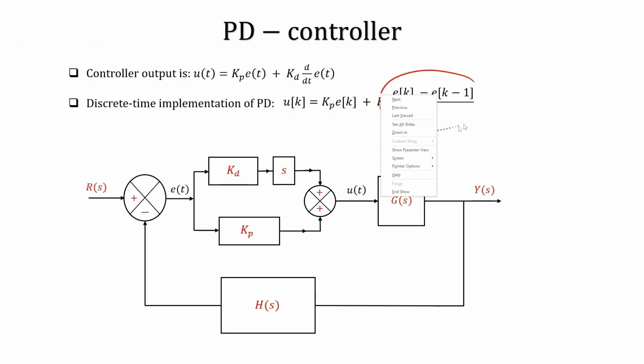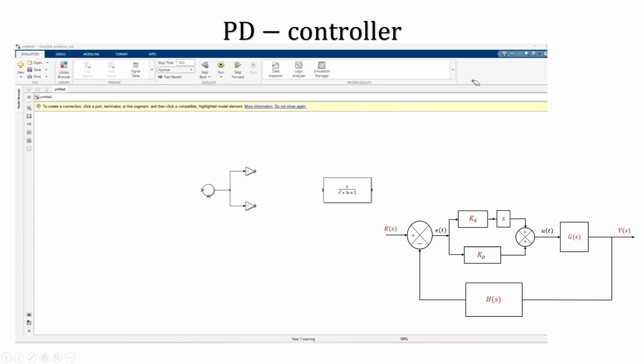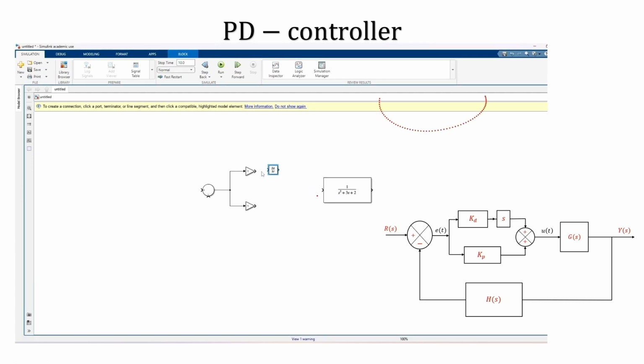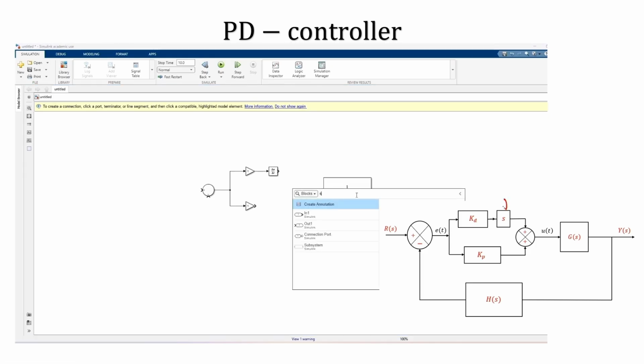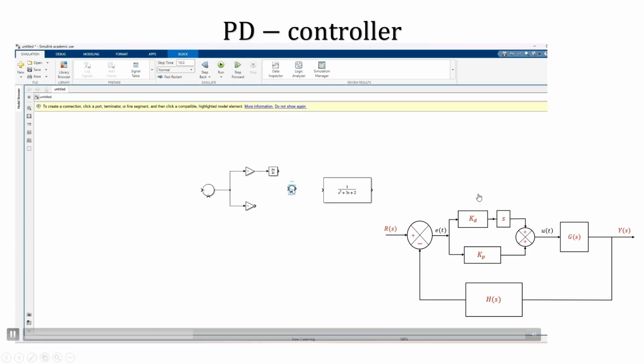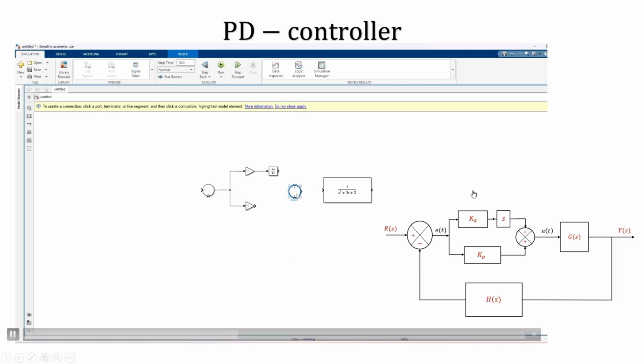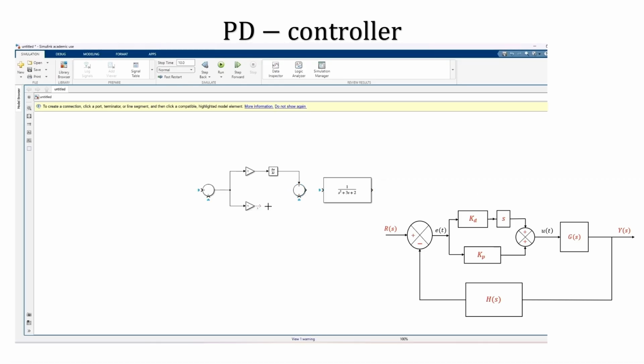Okay. Now, how do I ensure that this has been implemented? In Simulink, in place of the transfer function I can use what is known as a derivative block. It computes the approximate continuous derivative of a continuous function. Using this block you can implement the derivative part of the controller. You see, in Simulink there is a direct block by which you can implement a PID controller, but I am not showing you that. I just want to show you how to implement the PD controller in general. So now you will be able to implement this controller directly.